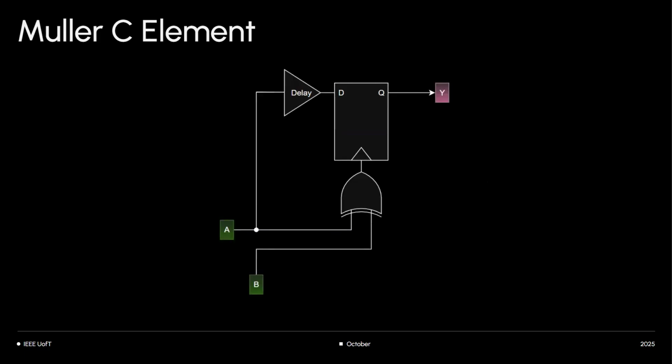What circuit components do we have here? Okay, sorry. Good job. Someone said a D latch. Yeah, you traditionally build it with latches, but I'm showing a flip-flop variant. This is something that I designed because you don't get latches that easily on FPGAs until you tweak their configuration.